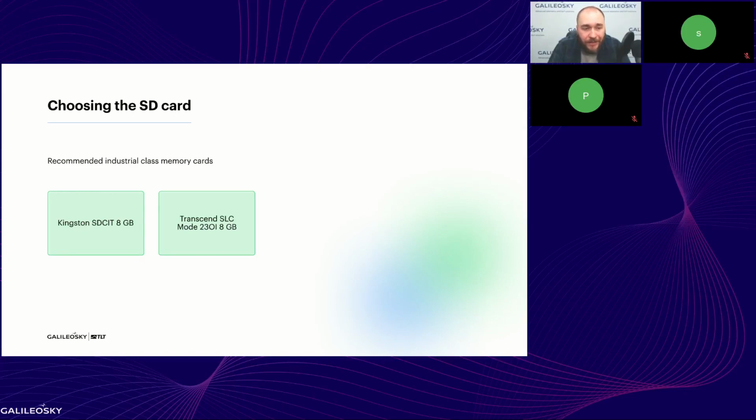They have much higher prices, but it is important to use industrial cards, because in case the microSD card is damaged, you will lose all the data collected by the hub from the clients. So it is better to buy high quality microSD cards, and you need to install microSD cards in most cases only in the hub devices, so it mustn't be an issue.